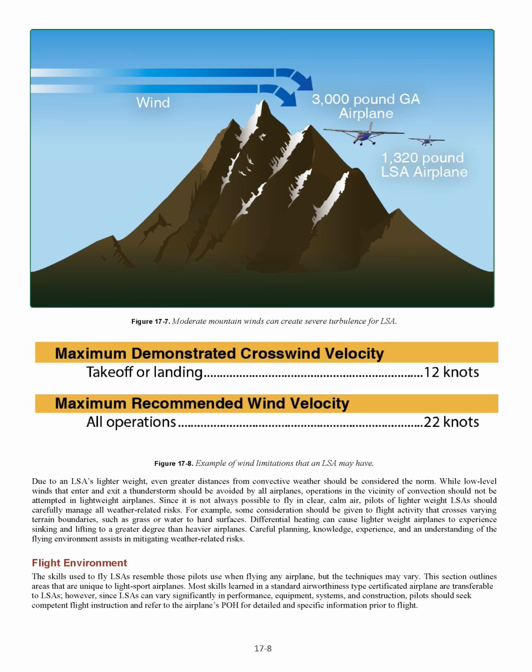Since it is not always possible to fly in clear, calm air, pilots of lighter-weight LSAs should carefully manage all weather-related risks. For example, some consideration should be given to flight activity that crosses varying terrain boundaries, such as grass or water to hard surfaces. Differential heating can cause lighter-weight airplanes to experience sinking and lifting to a greater degree than heavier airplanes. Careful planning, knowledge, experience, and an understanding of the flying environment assist in mitigating weather-related risks.